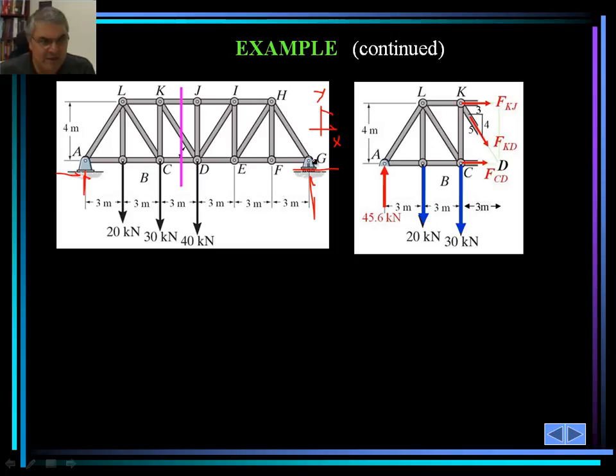So in that case, we take the summation of moment about G, knowing all the moment arms, we would have one unknown, which would be the vertical reaction, or the reaction in the y direction at support A, and we would calculate that as such.